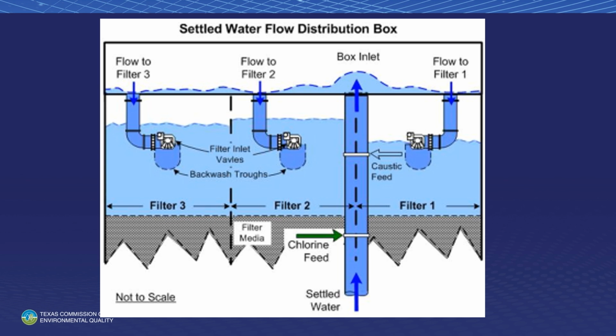So that plume of chlorine was dependent on the diffusion to spread out into that pipe. But it didn't have time to completely mix before it got to the pipe. So there was a concentrated plume of chlorine going up the side of the pipe. And when it got up here, all the chlorine went this way and fed into these 2 filters. And the water coming up this way, going that way, didn't have any chlorine in it at all.